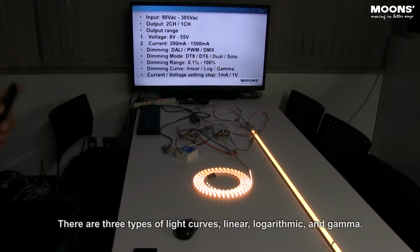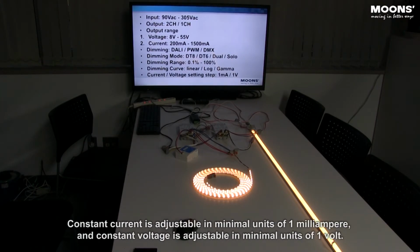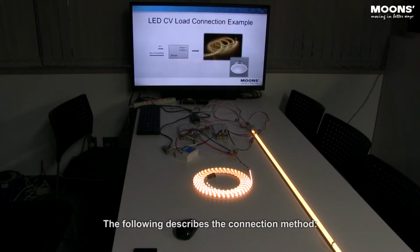There are three types of light curves: linear, logarithmic, and gamma. Gamma means the DMX method, while linear and logarithmic correspond to PWM and DALI. Constant current is adjustable in minimal units of 1 mA, and constant voltage is adjustable in minimal units of 1 volt. The following describes the connection method.